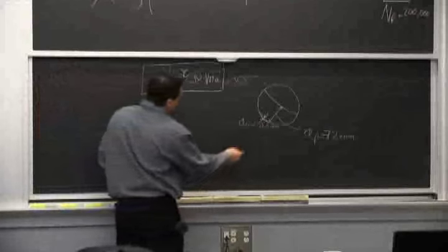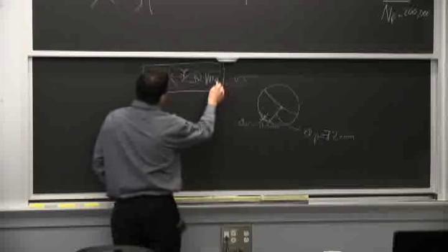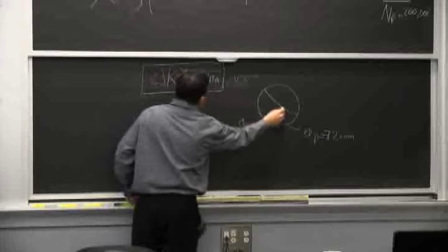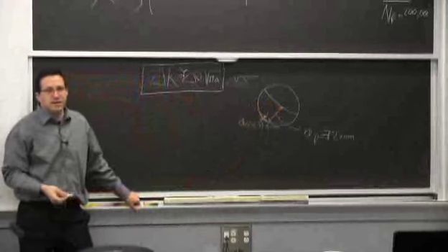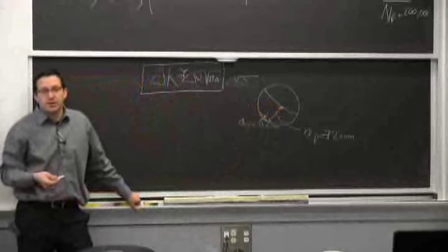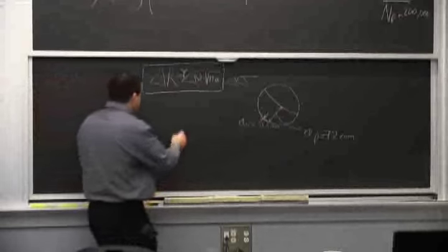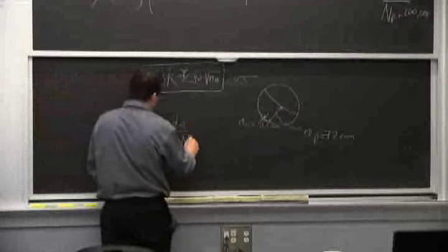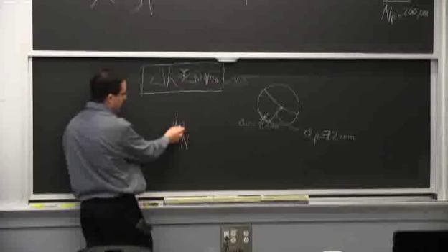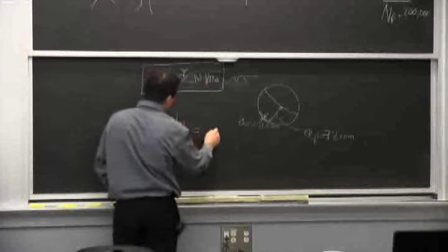So when we start here, a is smaller than when we finish here. Intuition tells us that the crack is going to grow faster. So we could just say, well, okay, I have dA/dN, which is my extension of crack length as opposed to number of cycles, equal to a fixed number.